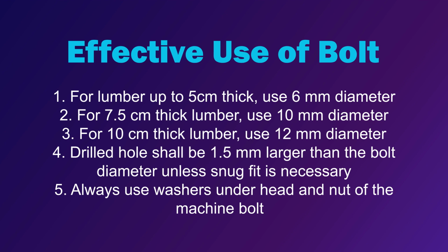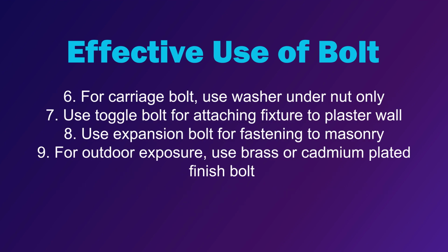Always use washer under head and nut of your machine bolt. For carriage bolt, use washer under nut only. Use toggle bolt for attaching fixture to plaster wall. Use expansion bolt for fastening to masonry. And for outer exposure, use brass or cadmium plated finish bolt.